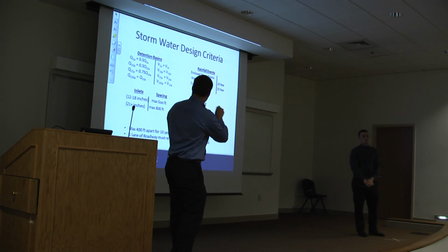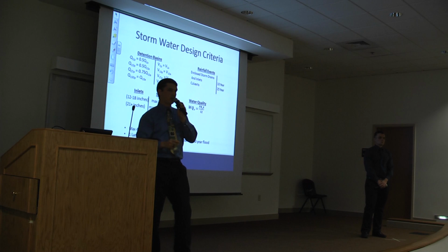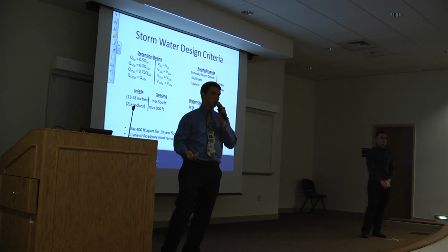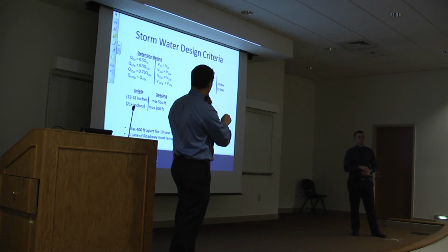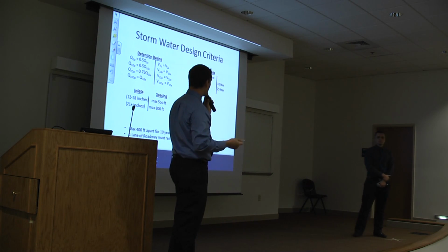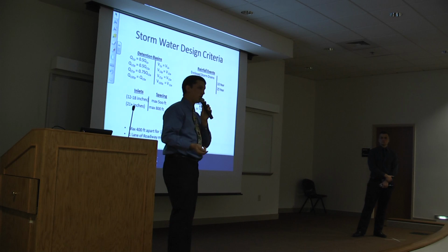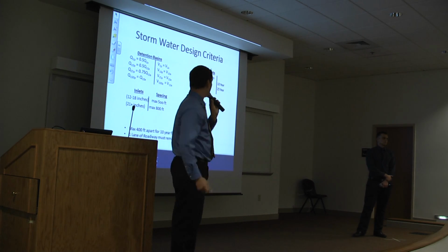So what this criteria is saying is not only do we have to meet the existing criteria on the site, but we have to improve the conditions. On the right, we have to design the inlets and culverts. We have to design the inlet for a 10-year flood and the culverts for a 25-year flood.